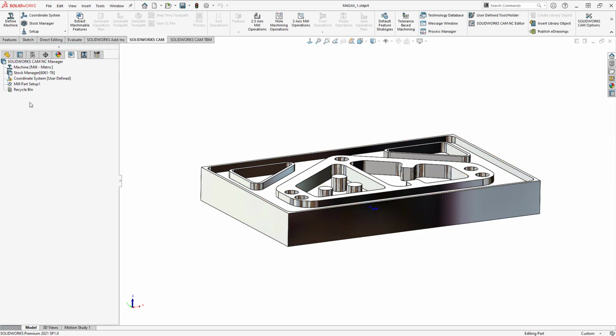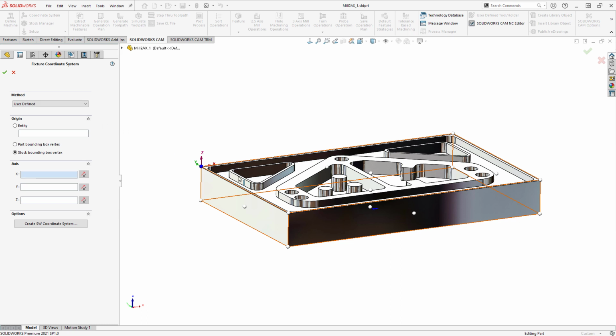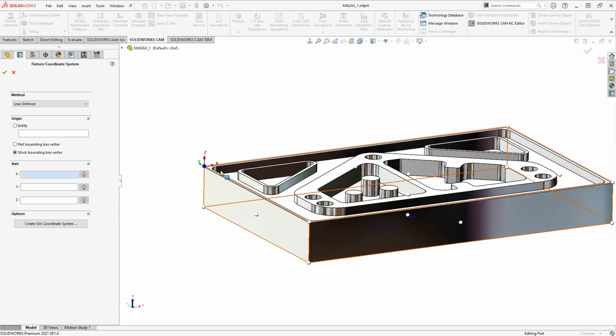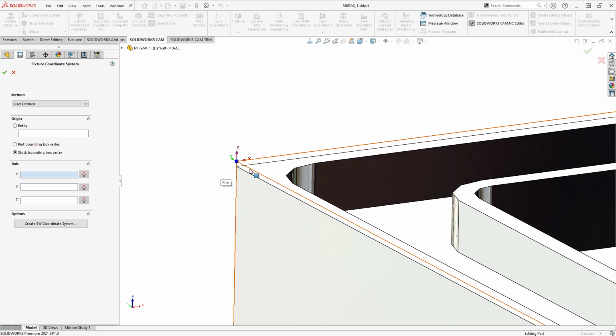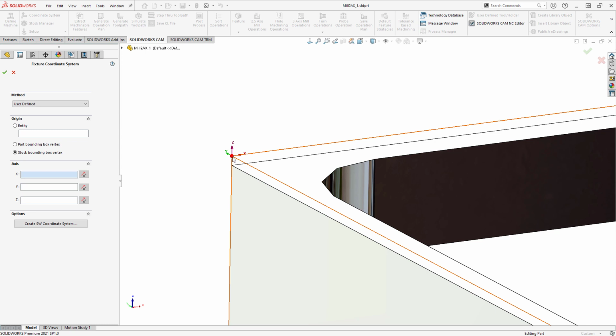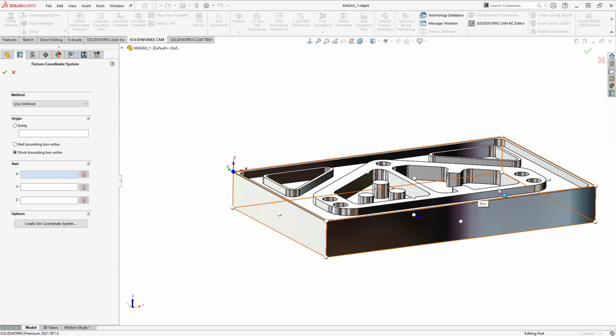We'll go ahead and hit OK to that, and then we'll go through and make sure we get into our coordinate system, which is going to tell it where to be, where to go, what is my Z direction, where's my 0, 0, all that stuff. And here, in this particular case, we're actually telling it to go to the upper left corner of the bounding box. And we can see that even though we added that 1 millimeter in there, it's already there at the right location. So we're in a good spot there at this time.